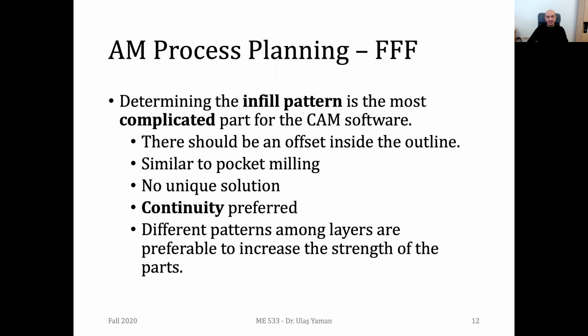Another thing about the infill patterns is that in order to increase the strength, assume that this is a kind of a layer. If you have vertical infill patterns for a specific layer, then for the next one, assume that this is the ith layer and this is the i+1 layer, it's better you have horizontal infill patterns, so that will actually increase the strength of your part.